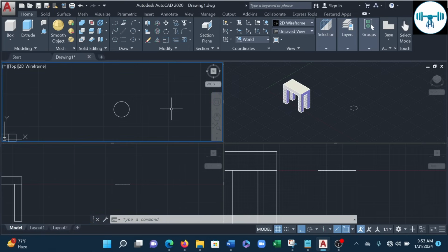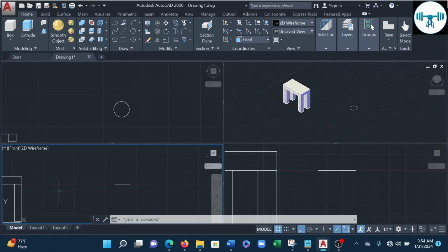So I get back to my top viewport. Now remember that the lower diameter of this funnel, if we decide to call it the leg or whatever, is going to have a height. Now what I'm going to do is come to my front viewport. I want to duplicate this particular circle through a particular height. Let's give the funnel a height of 7 mm.